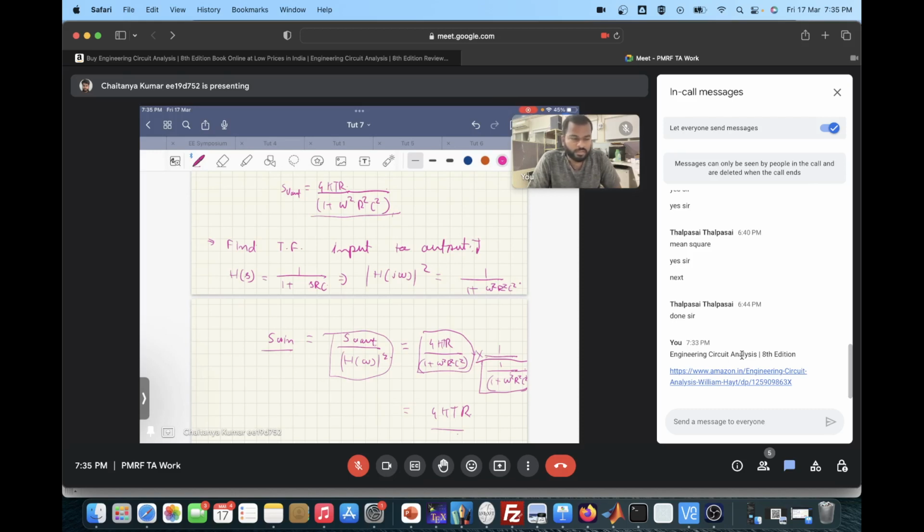You are mostly working on Verilog, then synthesis, then physical design and verification and all those things. Analog design, or even high performance digital, is mainly custom IC design. There you actually design the circuit, size each transistor by itself, and so on. So these two are completely different.